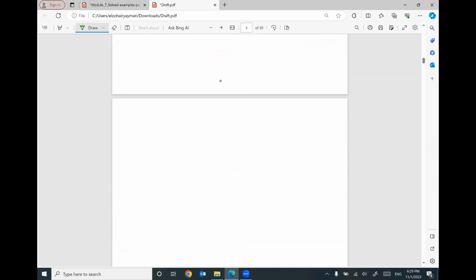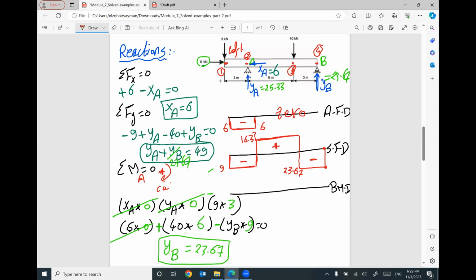Keep in your mind, the end of the beam is given without any given moment. So your value at this end will be 0. So M1 will equal 0. So your value at the beginning equals 0.